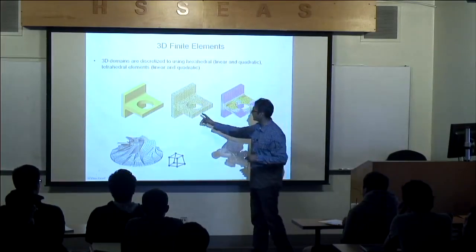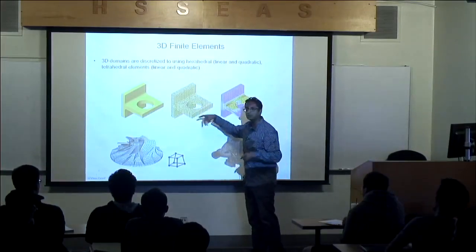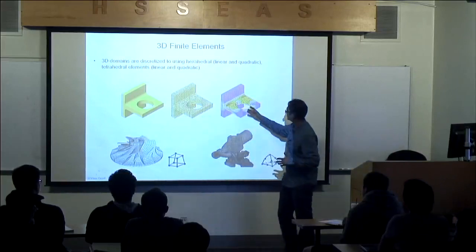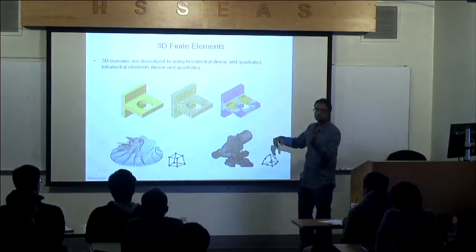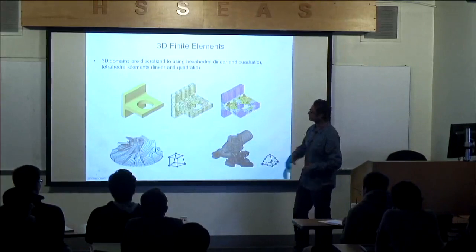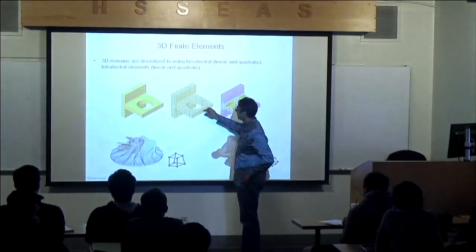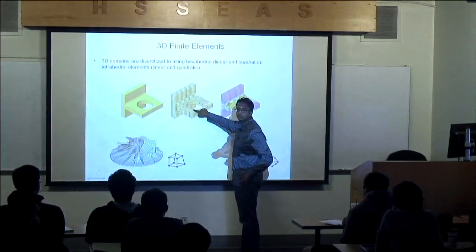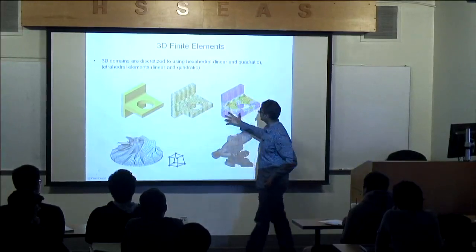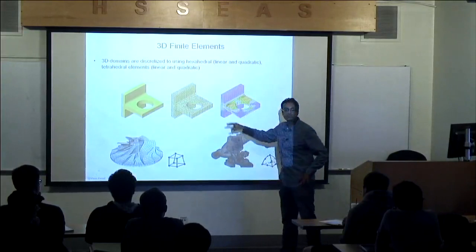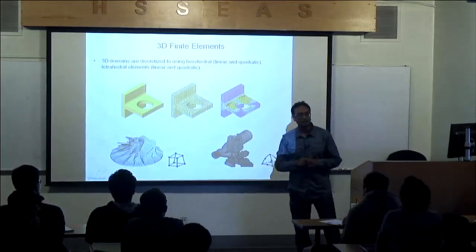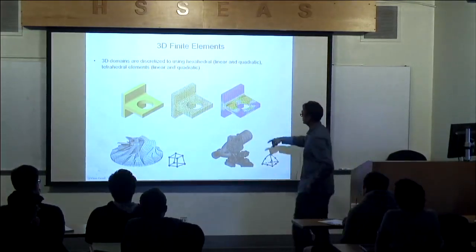Then you can assemble everything together, apply the loads, the boundary conditions, and then you will get the stresses of the system. In this case, there are two competing stress concentrations. There's one at the fillet radii, if I were to apply a load this way. And there's also a stress concentration from the hole. It turns out that in this particular problem, the stress concentration from the fillet radii is much more important than the stress concentration at the hole.